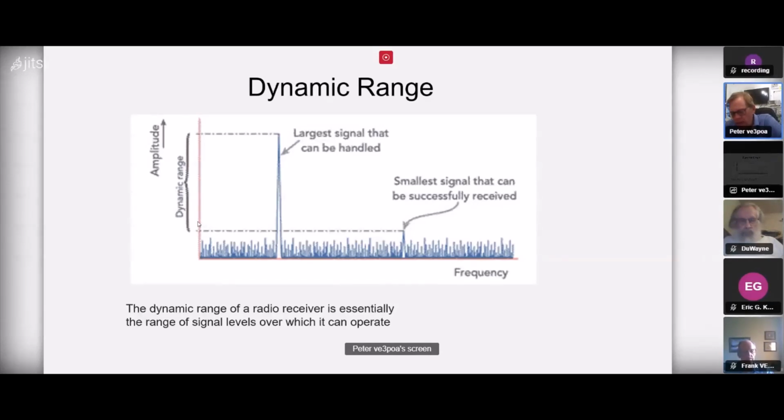An automatic gain control, AGC, circuit at the front end of the receiver can be useful in avoiding signal saturation and spurious signal generation. We do use an LNA in the Phoenix front end, but we have not incorporated an AGC circuit, nor have we really discussed it, but it's probably not that far down the line for the next generation. Okay, design for optimum dynamic range performance is not an easy task.